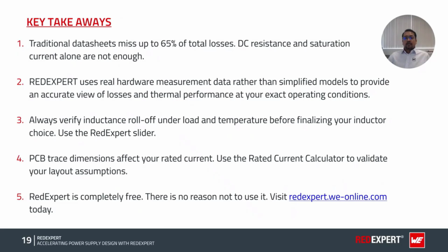Before I hand over to our partners at STMicroelectronics, let me leave you with the key messages from today's segment. Number one, traditional datasheets measure up to 65% of total losses. DC resistance and saturation current alone are not enough. Second, REDEXPERT uses real hardware measurement data, not simplified formulas, to give you the complete loss and thermal picture at your exact operating point. Number three, always verify inductance roll-off under load and temperature before finalizing your inductor choice.